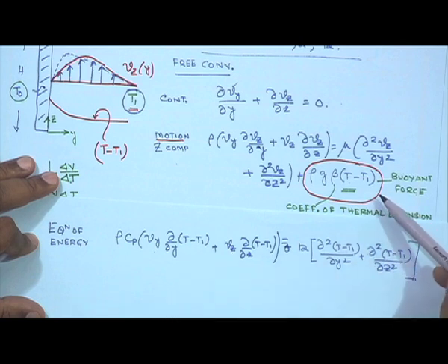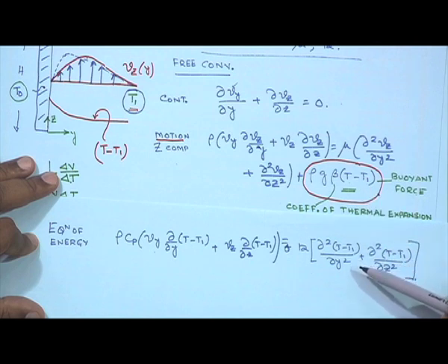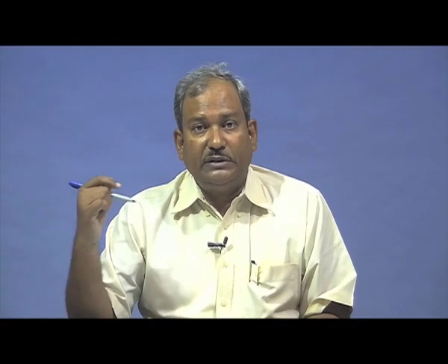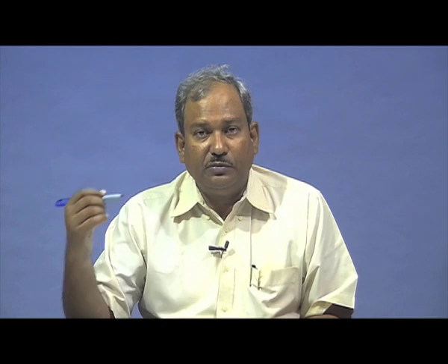However, the presence of the temperature term in both equations couples them in a more comprehensive way, in a way that we haven't seen before. So, the presence of the temperature term makes it a two-way coupling. You won't be able to solve either equation without solving the other one; both the energy equation and the equation of motion will have to be solved simultaneously. So, that makes it more complicated.